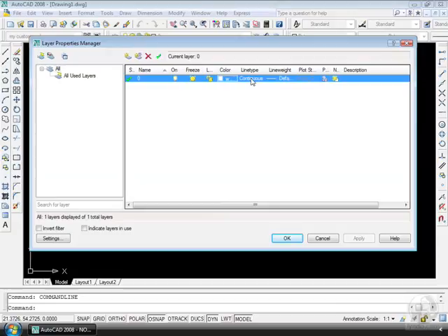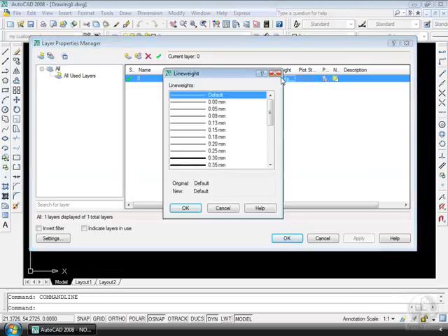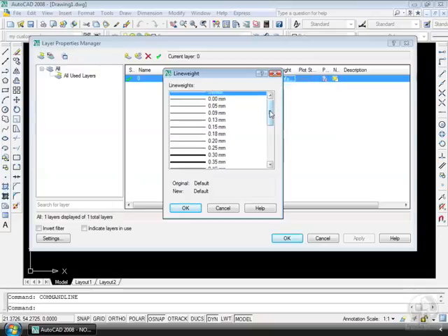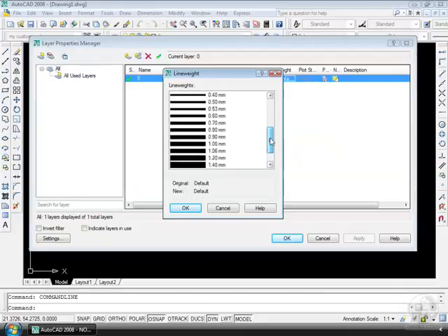I've got a line type selection. If I click here, I can set the line type for my layer. We'll get into this guy in just a little bit. Moving down, I've got the line weight area. If I click on this selection, I can choose a plottable line thickness or line weight for my drawing. We'll talk about this guy more when we get into plotting, but this is where we can adjust our plottable line weight. Let me close the dialog.